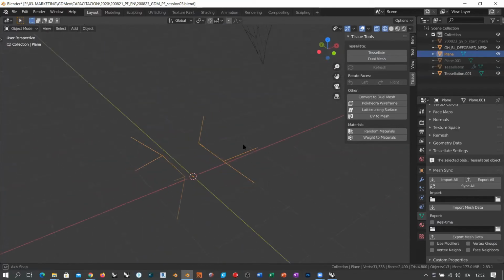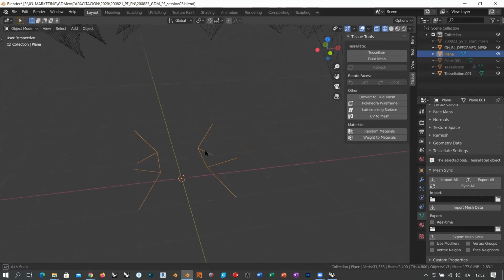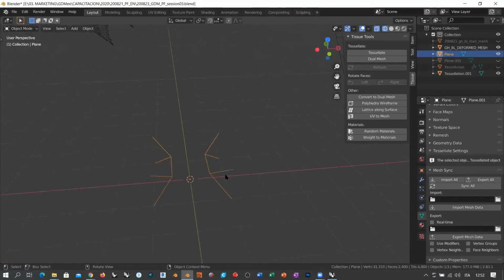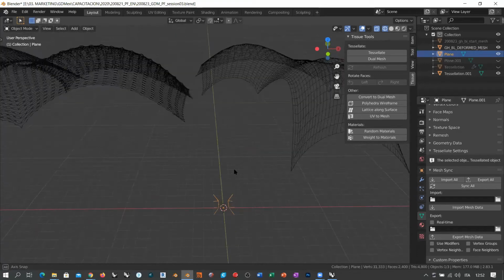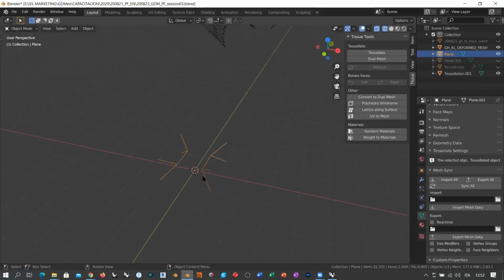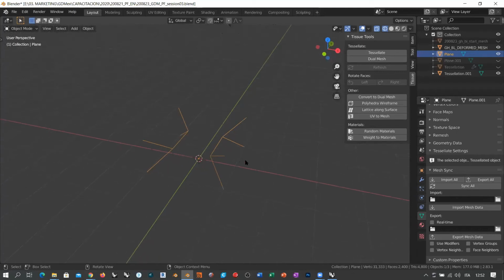It doesn't necessarily have to be this simple. You can work with more complex shapes, but remember that if you add many edges to this module, you will have thousands and thousands of edges coming out from the export. And then you will have very heavy calculation going on in Grasshopper from the shortest walk algorithm. So pay attention to this.